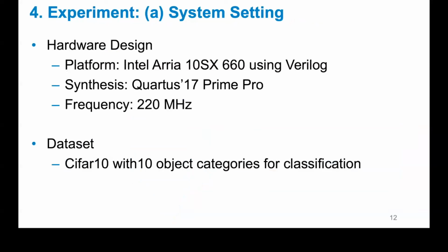Now we introduce our experimental part. The hardware design is implemented on the Intel Arria 10 SX660 platform using Verilog. Quartus is used for synthesis and the clock frequency is 220 MHz. CIFAR-10 is used as our dataset with 10 classes for classification.